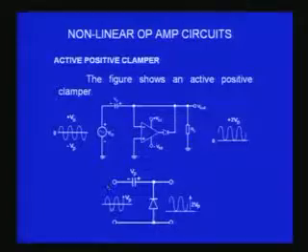So what is going to happen is, you have now a new situation where the input signal is applied in series with something like a battery. The capacitor charged to the plus Vp and the diode open circuited acts like a normal DC battery of a value Vp. So you have to now add this Vp to every instantaneous voltage of the input signal, and that is what you get as the output.